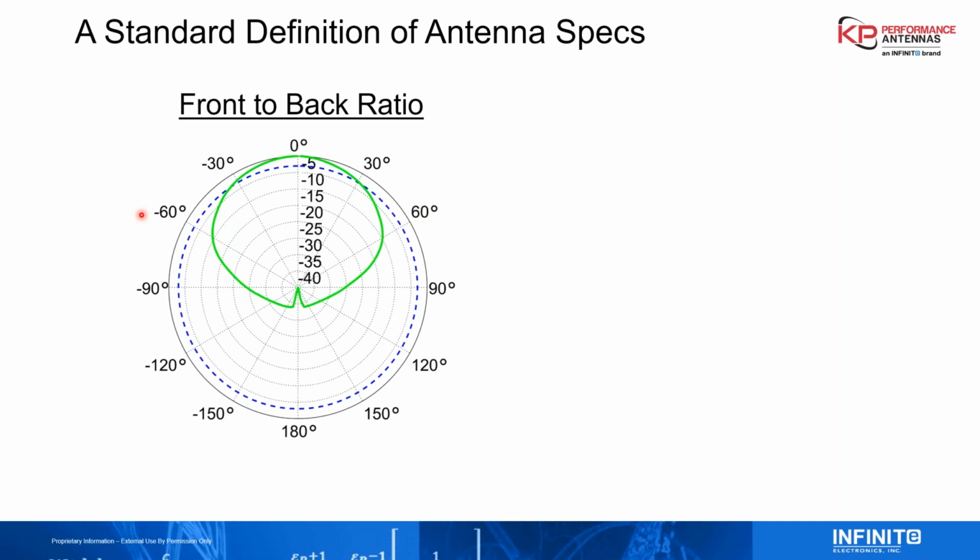Now, front to back is often just defined as the radiation pointing backwards at 180 degrees. But this is not a really useful parameter, because that only tells us that if you have an antenna right at 180 degrees and you're not trying to serve anyone between, let's say, -50, -150, and +150 with another sector back to back here,